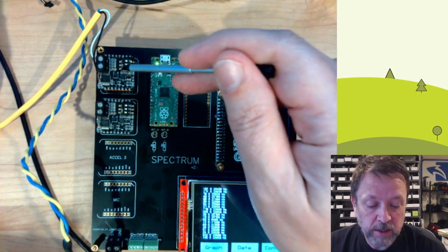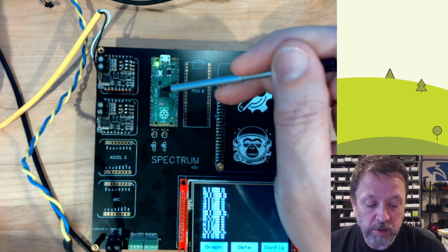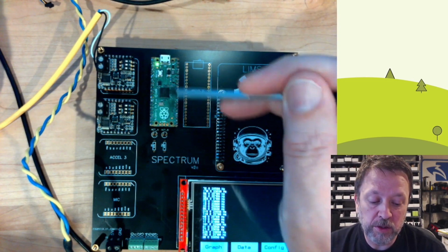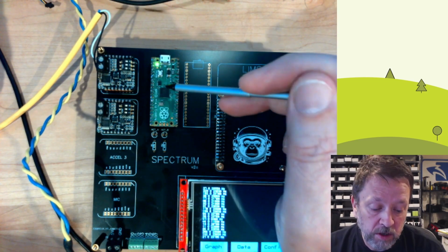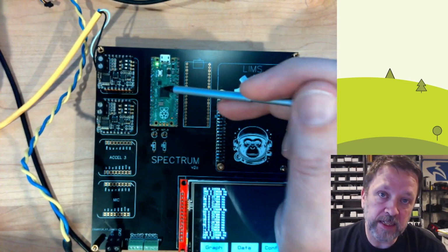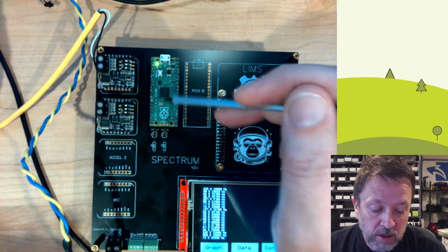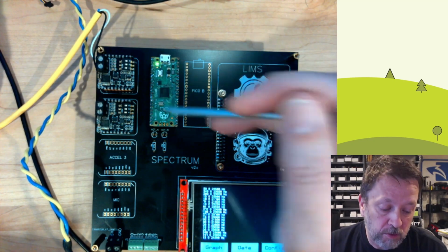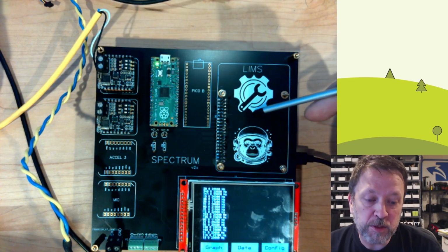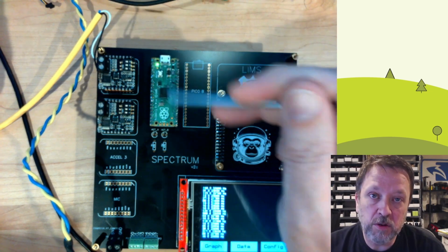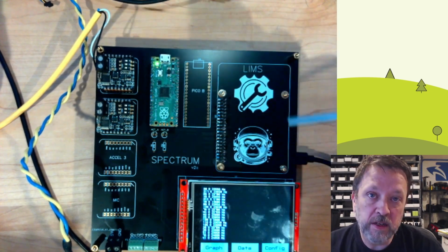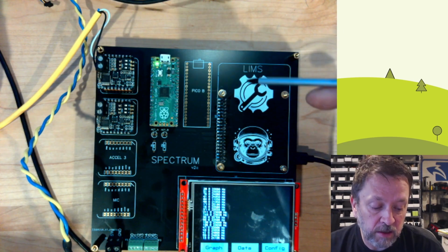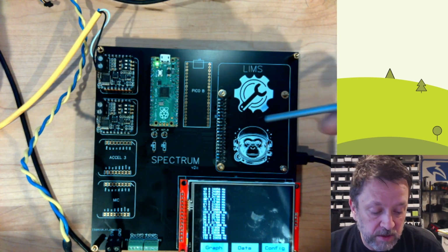So we've got 2 channels go into the Pico. The Pico is doing FFT on one core. It takes that data, passes it to the other core. That other core streams it over serial over to the Raspberry Pi. This is all written in C. And then the ingestion over here on the Raspberry Pi is written in C#.